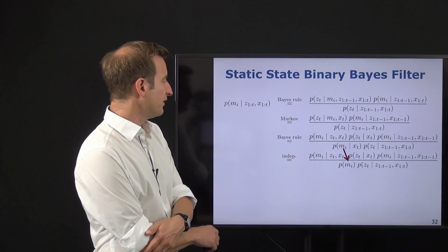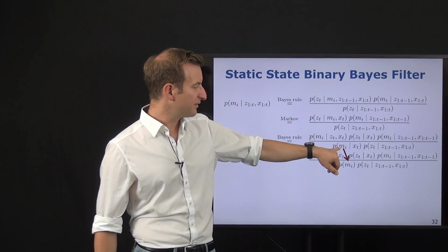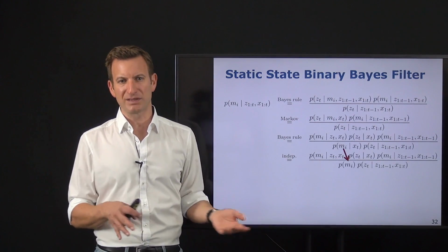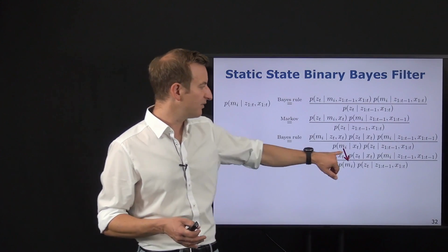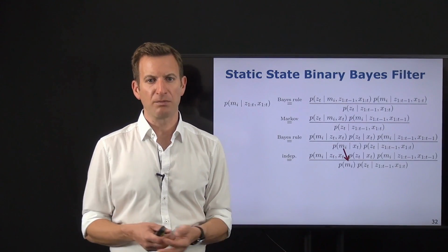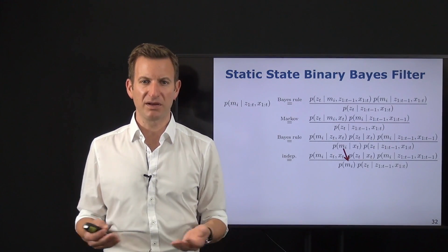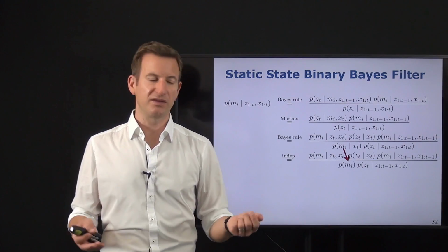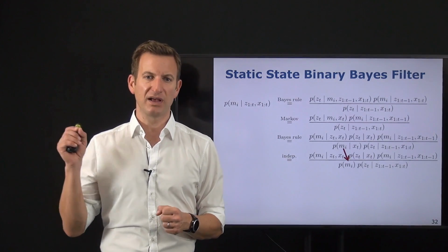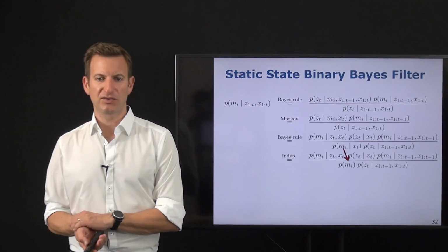But what we can do is first, using an independence assumption for this term, as I just mentioned briefly, say the probability of a cell being occupied, given I know where the robot is but have no idea what the robot sees or senses, doesn't really help me unless the robot is standing in that cell. But let's ignore this. So we can drop xt here and this just turns into the probability of a cell being occupied or free in general. This is basically just the statistics about the environment: do I have more free cells than occupied cells? This is what this prior encodes: if I just draw a random cell, how likely is the cell to be occupied or free? This is the map prior, so to say, that we have.